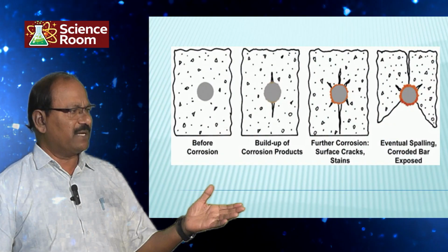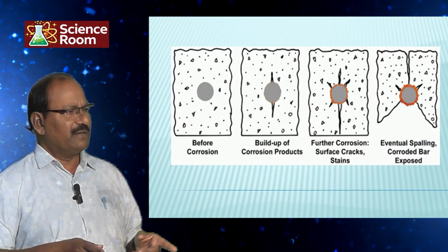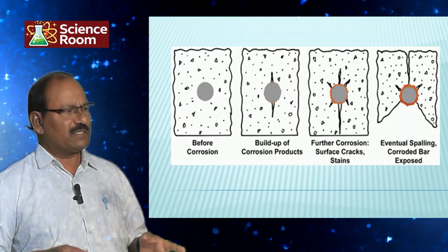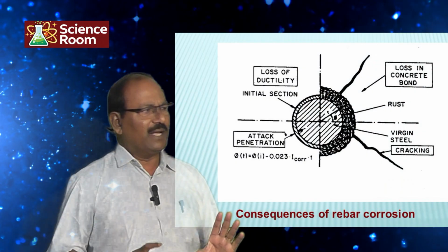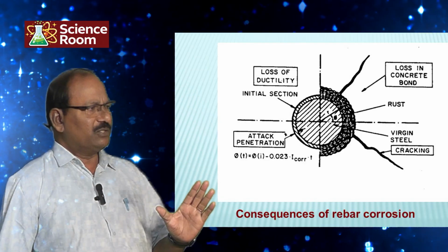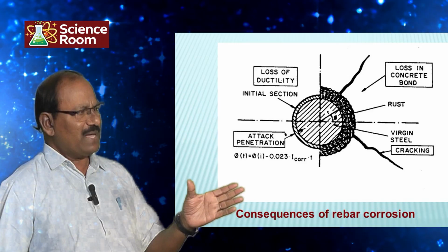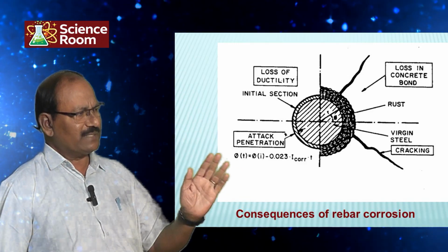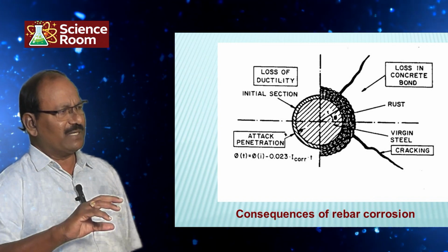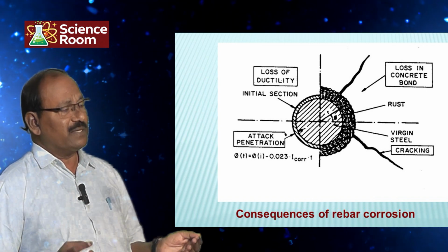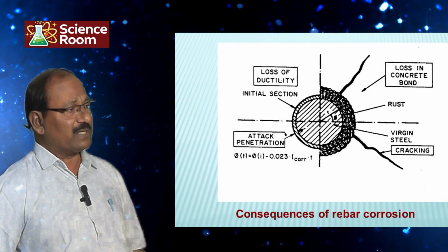And this is also the same thing. Wherever the pores and voids are there, the rust product also travels through them. This is corroded steel shown on two sides. One is the bare steel, which initially was like this, on the left hand side. On the right hand side, the rust product is being built up, and the bonding of the rod with the concrete is highly important.